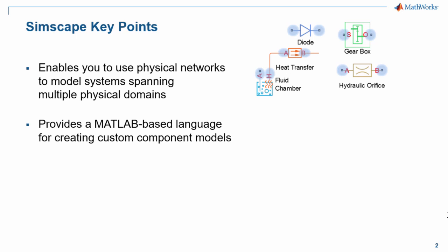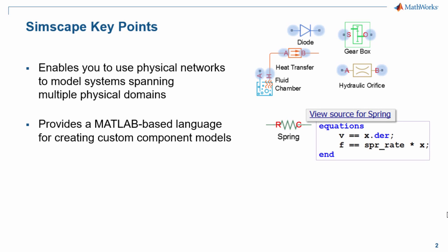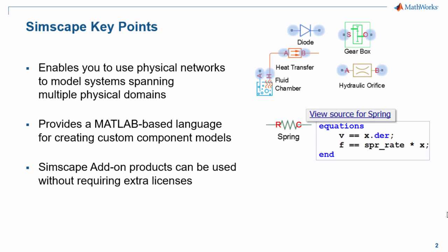Next, we'll see that Simscape provides a MATLAB-based language for creating custom component models. The component models in Simscape are defined using the Simscape language. This language is based on MATLAB, and you can use it to create your own physical components and define custom physical domains.